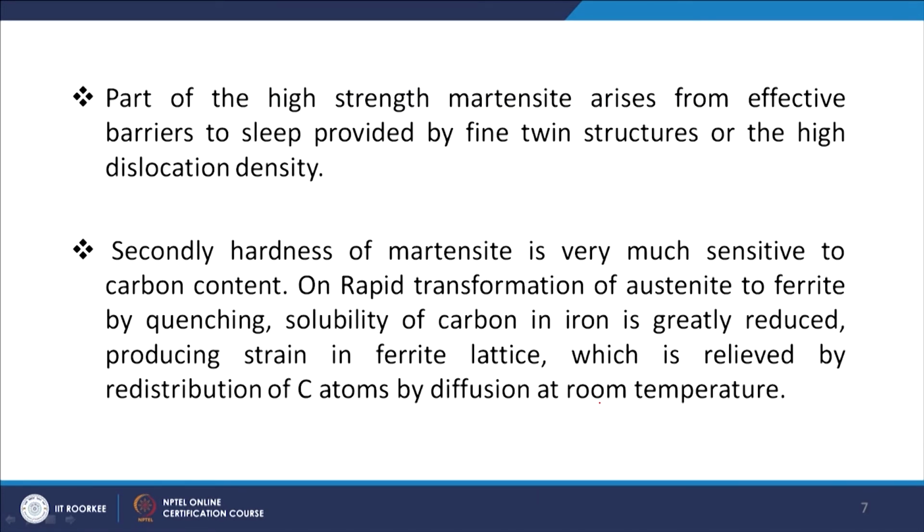Now, part of the high strength of martensite arises from effective barriers to slip provided by the fine twin structures or the high dislocation density. So, as we have seen, either you have the barriers to the slip provided by the fine twin structures or the high dislocation density. So, that way your high strength is coming.